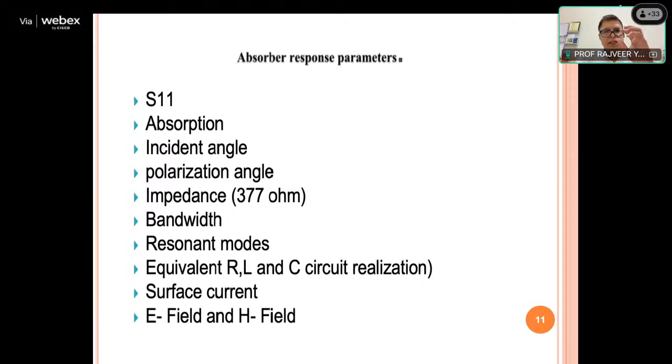This is the crucial role being played by antenna designers. With the help of playing with these modes, as I already said, the antenna can be made a multiple band antenna. The same antenna can be converted to a wideband antenna by merging of modes, or by splitting modes, a multi-band antenna. So mode generation and control is very important as far as design parameters are concerned.